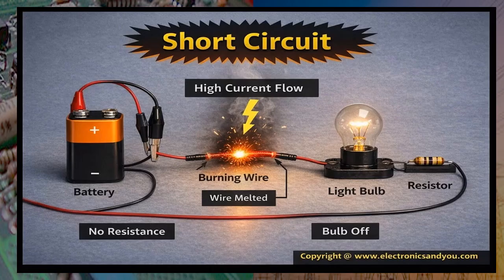Mostly for short circuit, you must understand the basic definition of a short circuit. That will help you to understand a complex problem. Short circuit is when there is a fault in a circuit and the current takes the shortest pathway to the source, or a pathway that does not have any load. So the current will take a short pathway, bypassing all the loads and back to the source in short circuit condition.